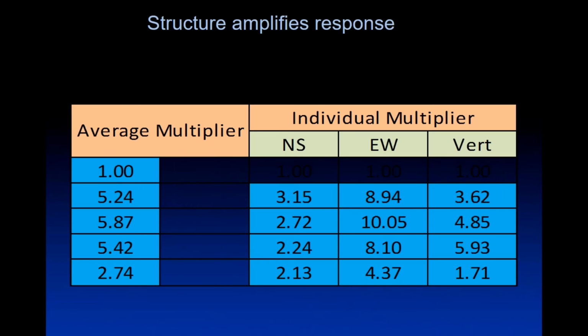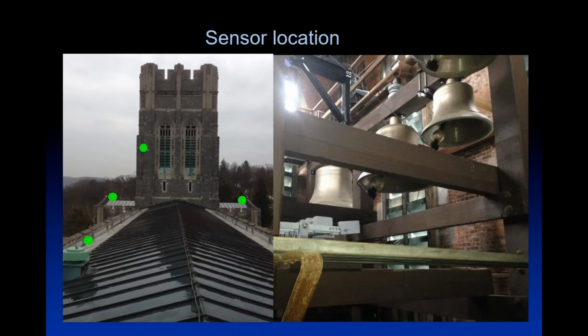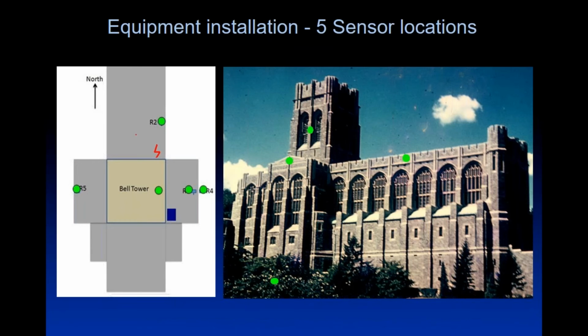So we looked at the relationship between these things. And we found this, measuring in different positions, a dynamic magnification factor of 10. Now, remember, we've got criteria that say 0.5 is what you aim for. 2, you might get damage, it's the threshold. 5 is certain damage. So 0.5 times 4 keeps it below 2, and everything is okay.